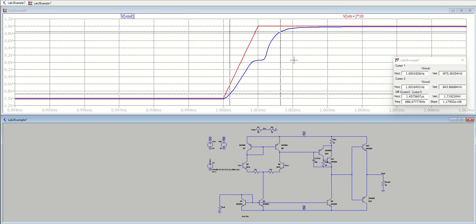So if you want to measure slew rate, you're going to need to develop a Class AB push-pull amplifier for your output stage. Otherwise, you're going to have a really difficult time measuring slew rate. For the Class AB amplifier, you're setting a DC bias point here of about 0.7 volts, just enough to turn the diode on for both of these transistors, and that will help the crossover distortion go away.